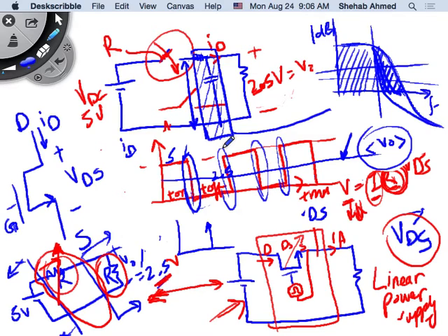But if you are doing 3D printing, building the latest and greatest 3D printer that is micro-positioning the extrusion process at 16 microns resolution, the extrusion process is driven by a heater and its positioning is driven by a motor. They are supposed to operate with very high resolution. If I'm not delivering precise power to the motor and the extruder, I will not be able to meet this 16 micron resolution.